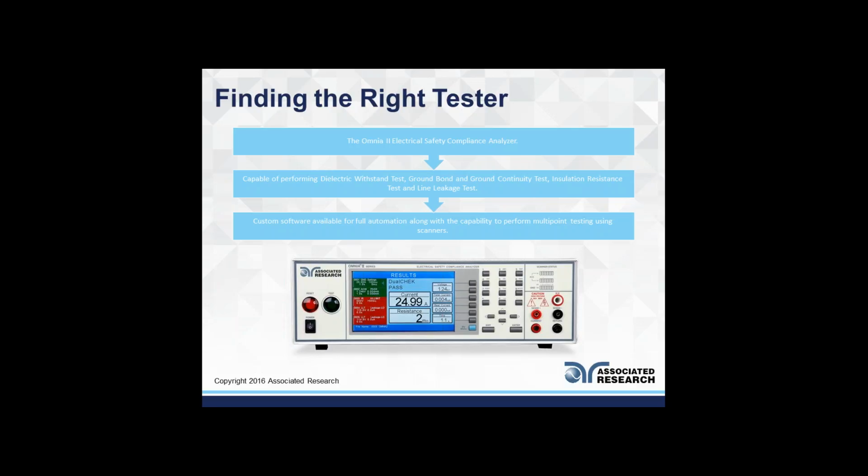Some of the standards also require what we call a 500 VA requirement. The 500 VA requirement is to ensure that the tester is capable of outputting at least 100 milliamps of current, to make sure testers that can't do this are not falsely passing some tests.